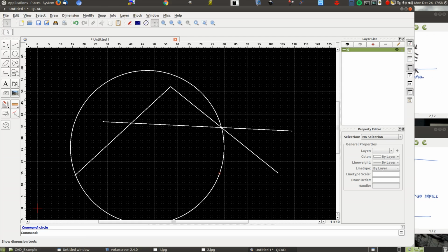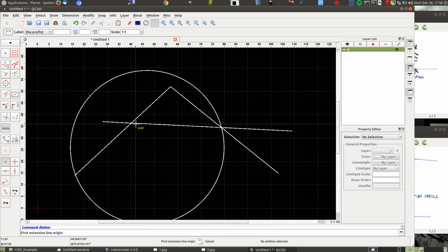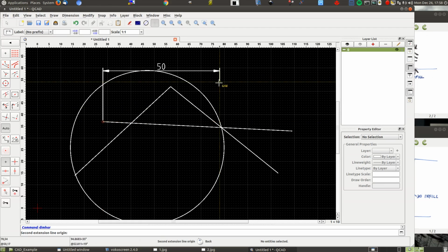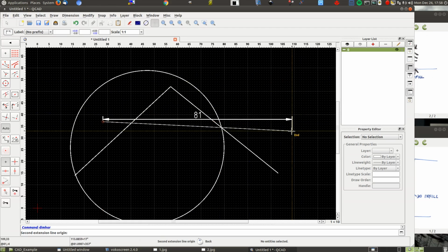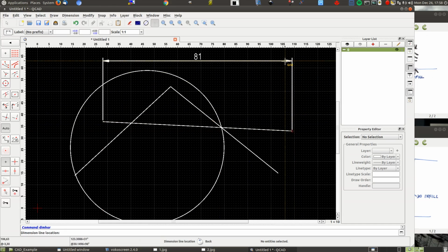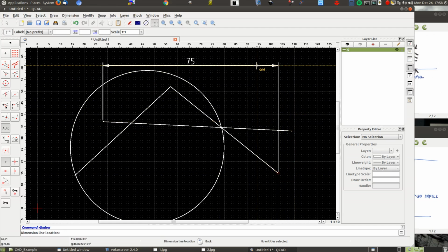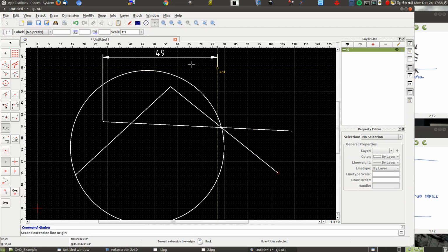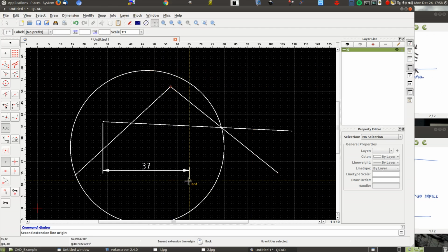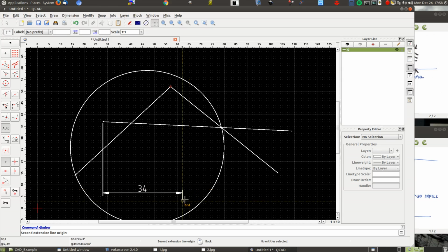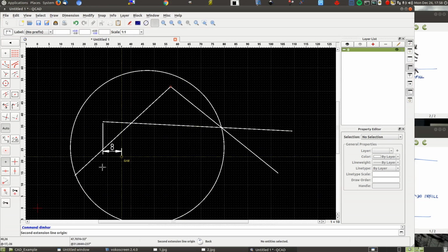Let's say I was to do a dimension. Here's one thing that it's quite good at. I start drawing a dimension line. Let's say I pick on that spot and I go over here, and that's the wrong spot. I right click, it releases that. Click on this other spot. Oh, no, I don't want that one, I want that one. You know? And so right clicking just lets you step back one step. It's very, very fast, very hard to beat this kind of performance.